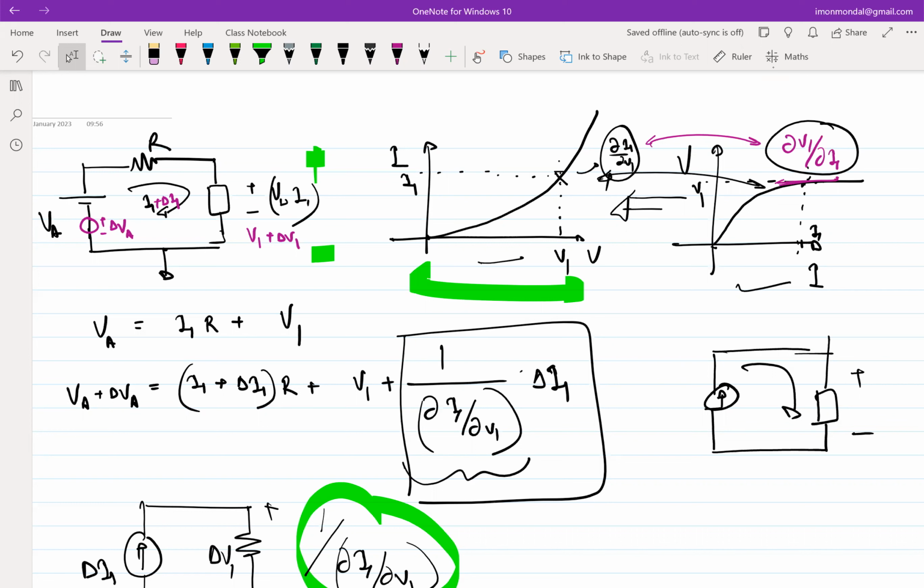Because the incremental voltage will depend on the incremental model. The incremental model of a forward bias diode is a resistance. So when I ask you for an incremental voltage, you have to replace the diode with a resistance. But if I ask you for an absolute value of the voltage, then you have to take into account the operating point of the diode also. At that time, you cannot simply remove the diode and put a resistance, right?